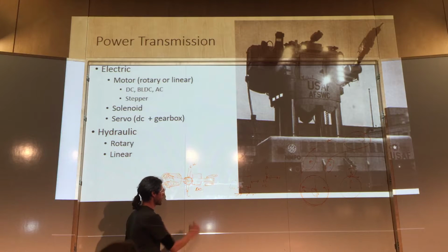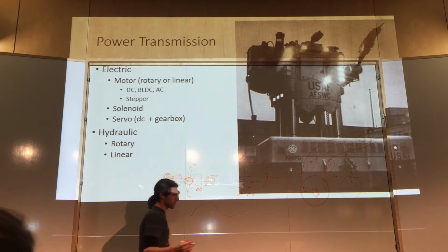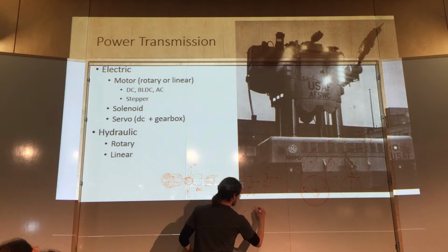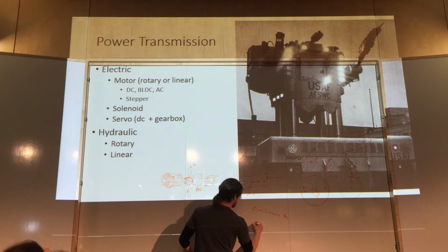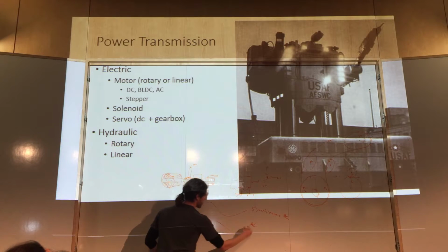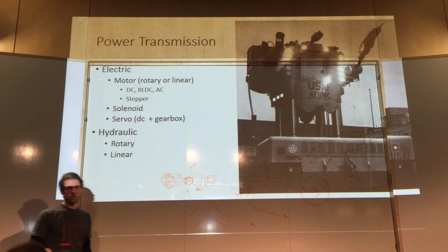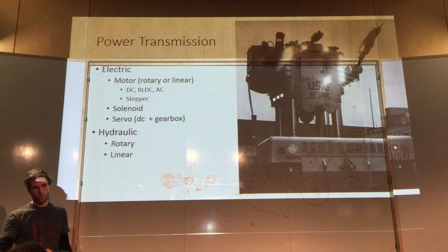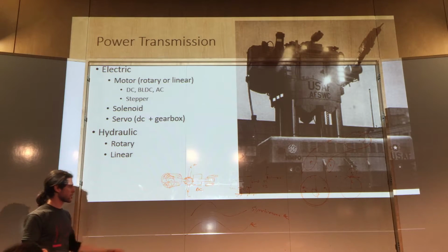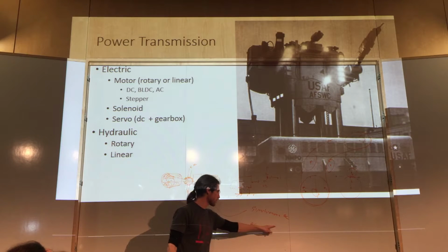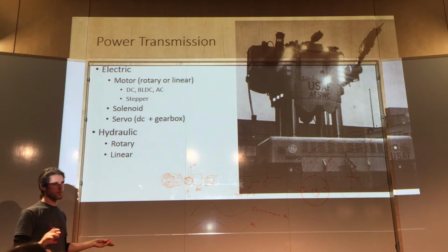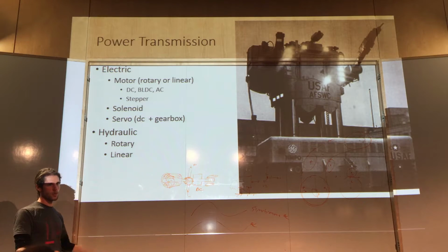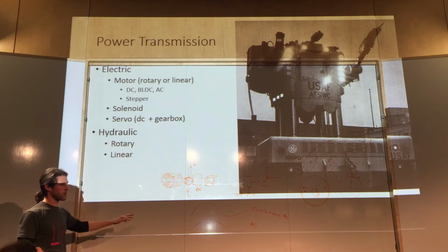It's just that the AC waveform, there's synchronous AC, and then just an AC motor. An AC motor just plugs into the wall, and this is like what your fan is. If you just have a wall fan or a box fan, it just takes the AC waveform that's coming through the wall, the 60 hertz, and uses that for commutation and spins the motor at some standard speed, and so that's just controlled speed. The only way to change that is to have a variable transformer.